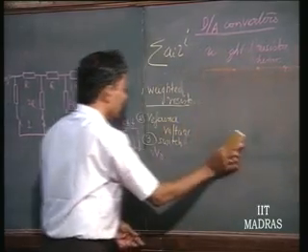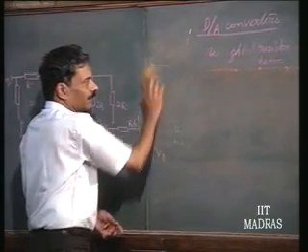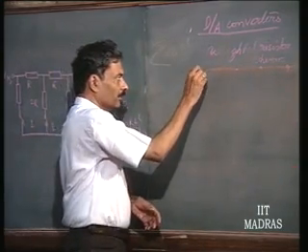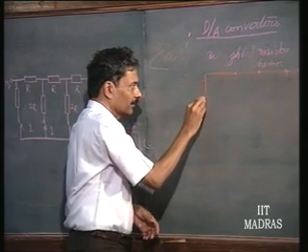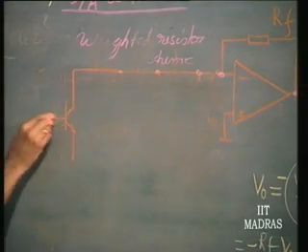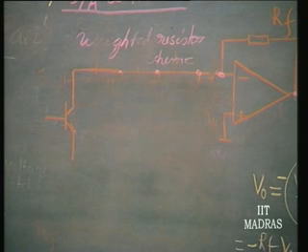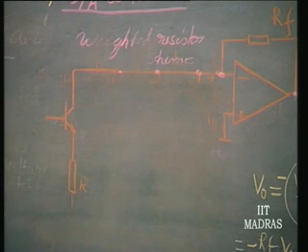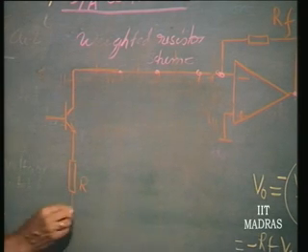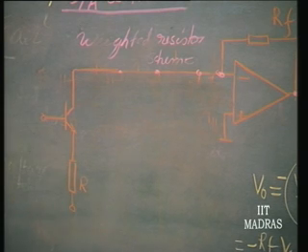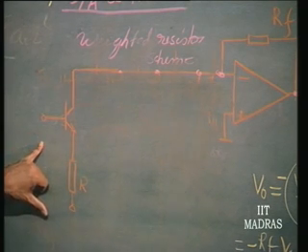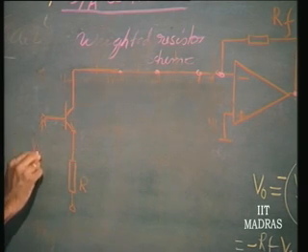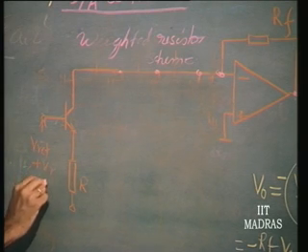So, instead of this kind of scheme, what is therefore recommended for avoiding the error due to the switch resistance, why not use a current source, let us say a transistor current source. Okay. And now you will put the resistance here, okay, and appropriately apply a voltage here, which is maybe V reference, okay, plus V gamma, so that V gamma is given. So, the voltage that you apply here is going to be V reference plus V gamma.